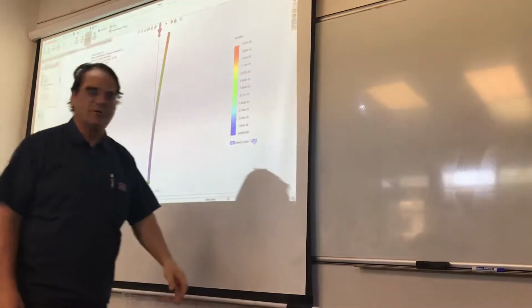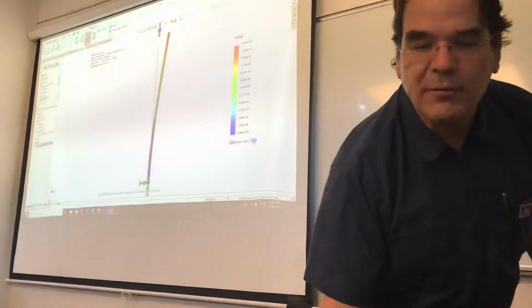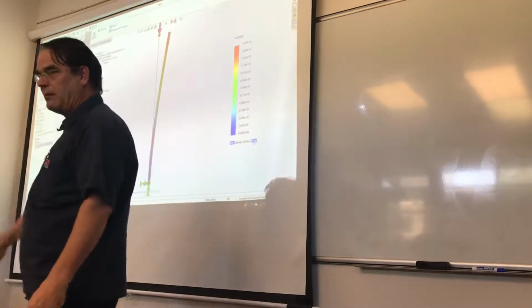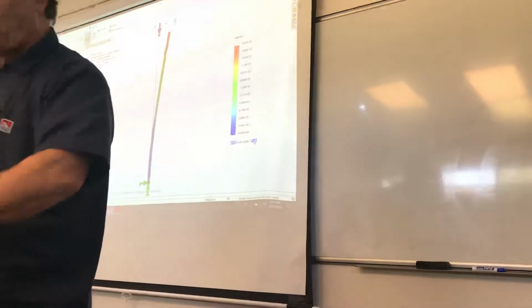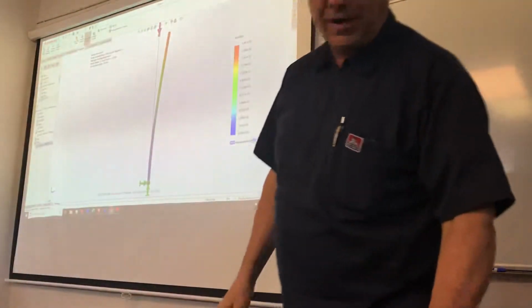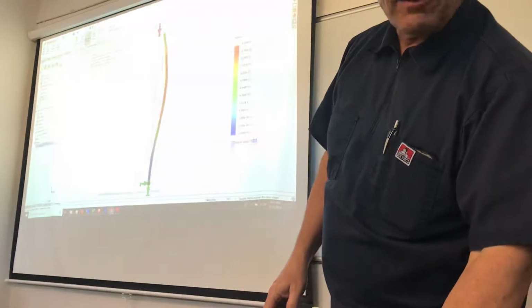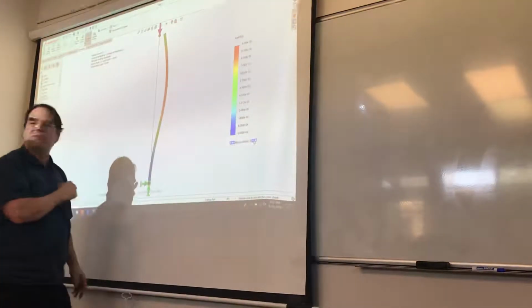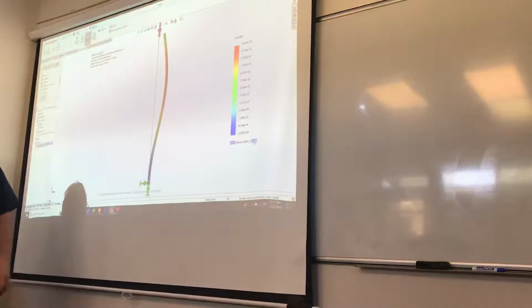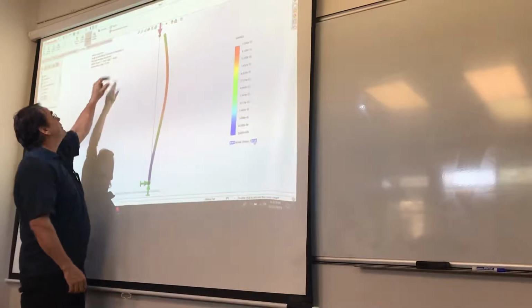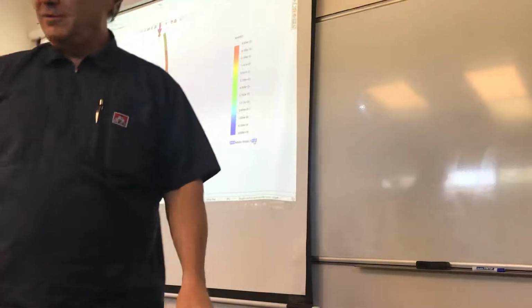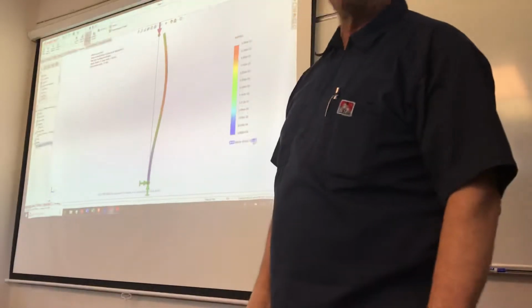And when I do the second one over here, which they actually allow me to click at, it does the same thing, it's just doing it in a different plane. It's making just one big curve here. Now, they don't really get interesting until we get to the third ones. Now, what is it trying to do? Well, now we're making an intermediate curve. This is the third mode, and if you notice, our safety factor, or our load factor, went from 6.5 to some much larger number.